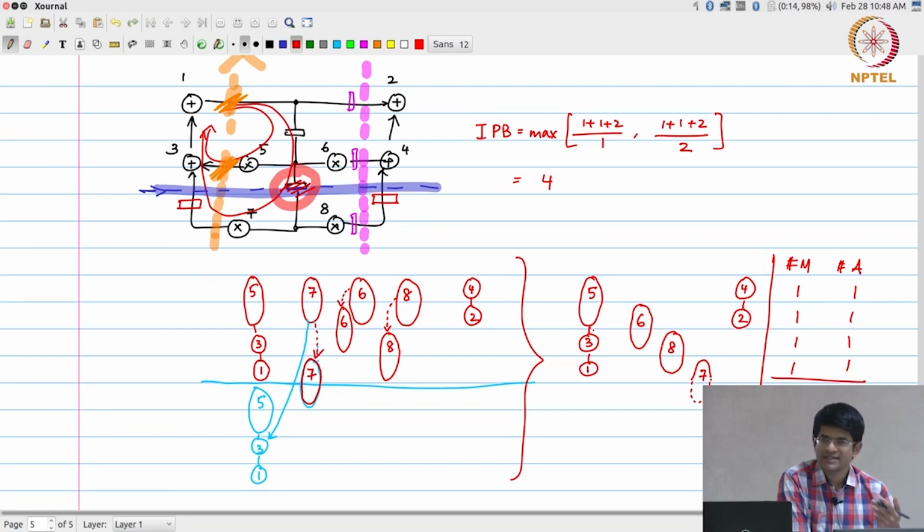Okay, so scheduling essentially talks about how we systematically take a data flow graph that we have and get different kinds of hardware architectures, or given an architecture, get a different allocation of operations to hardware units, such that the hardware utilization is kept good, and at the same time maybe the total latency, or the time required for finishing all the operations, is kept to a minimum. Okay, you will notice that I am not talking about optimum, that is to say the best possible way of doing it.